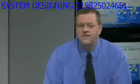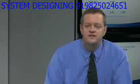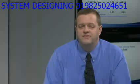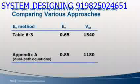It should be pointed out that the standard does not require you to use Appendix A for these dual-path systems. As long as the largest zone outdoor air fraction is less than 0.55, you could choose the much simpler approach of looking up system ventilation efficiency in Table 6-3. However, realize that the default values in that table do not account for the unused outdoor air in the secondary recirculation path. So the result will be a higher intake airflow. Quite a bit higher in our example, 1,540 CFM if using Table 6-3 versus 1,180 CFM when using the appendix.